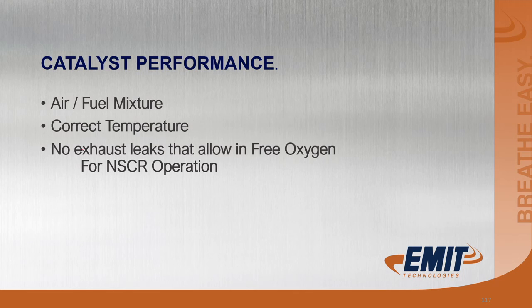And then the last thing is, and probably the number one thing that we see out there, is no exhaust leaks that allow free oxygen in the exhaust stream. And this would be strictly for the NSCR catalyst operation. For an oxidation catalyst, we're not worried about the oxygen.